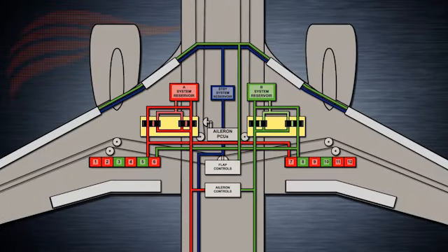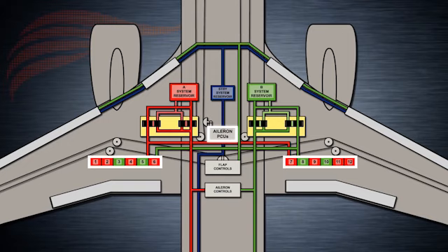Similarly to ailerons, the flight crew uses the control wheels to control roll with spoilers. The control wheels give mechanical input to the aileron power control units, PCUs, through the aileron feel and centering unit. From here, the PCUs supply mechanical input to the flight spoiler actuators that use hydraulic power to move the flight spoilers. The control wheels must be displaced more than 10 degrees left or right to actuate the respective set of flight spoilers. System redundancy is provided in the following manner.